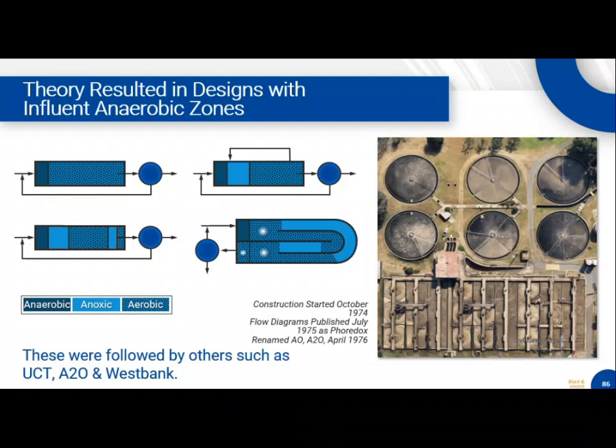So the Clean Water Services example I had, where I said they were very carbon limited, they have 10 different zones along the length of their aeration basins with walls and mixers and diffusers, because they have to be very precise in where they add their RAS and where they add their VFAs, because it's a very limited resource. That carbon is the limited resource for a biological nutrient removal facility, and we can't be wasteful with it.